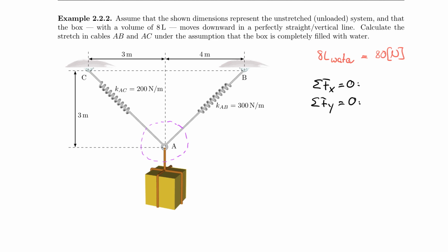And therefore, I can only solve 2 unknowns at a time, because if I have 2 equations, I cannot solve more than 2 unknowns. Or likewise, if I had 3 unknowns, I could not solve that with two conditions. And that is why when you draw free body diagrams and when you cut the system, you always have to make sure that you only cut through two unknowns.